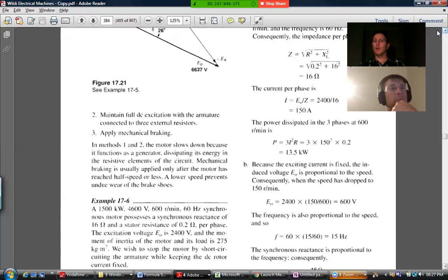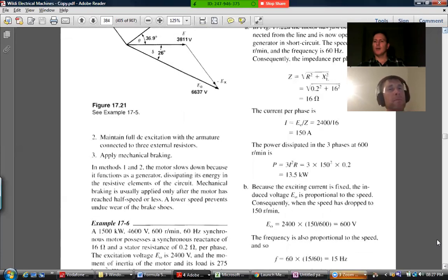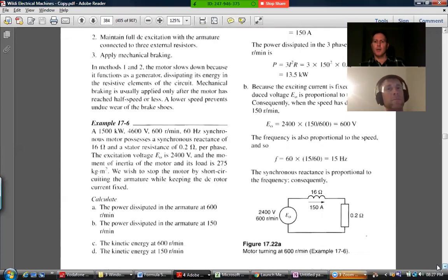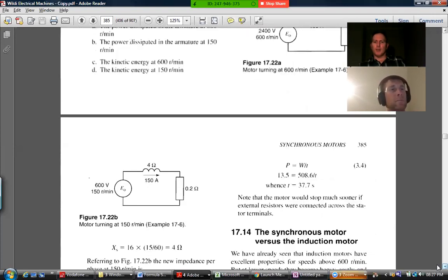But yeah, slowing down a big machine, it can be necessary to actually put in some resistor bank to allow I squared R heat to be generated, which is then extracting that energy out of the half mv squared essentially of the actual big heavy rotor that's spinning, or the load that's spinning, for that matter. Which brings us to the end.